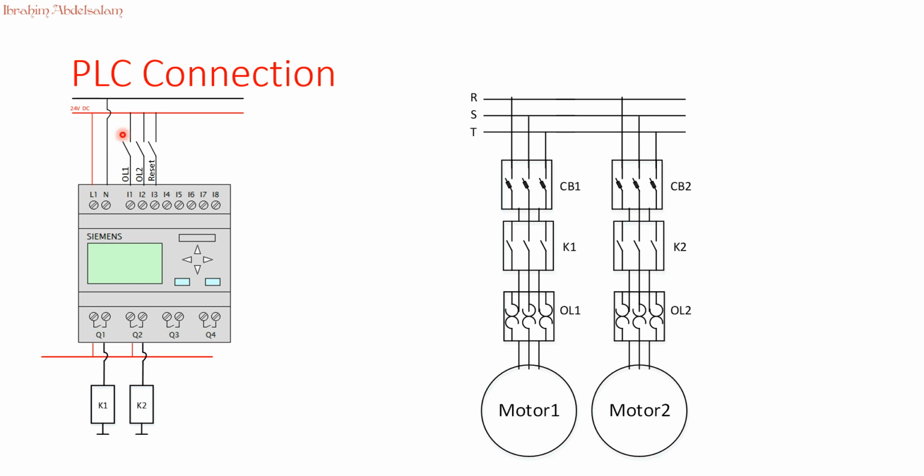In this case we choose a normally open contact, so we receive an overload signal. Once the overload signal is received, motor 1 will have to stop immediately and the user can't turn it on again until the user presses the reset button. So in this upgrade we'll have three more inputs: overload signal 1, overload signal 2, and the reset button.